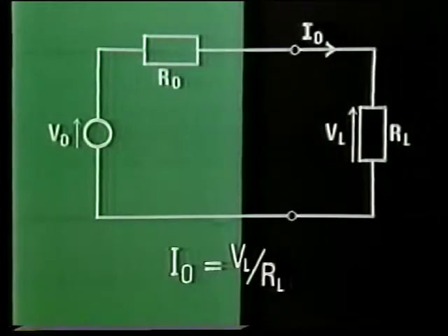If the voltage gain, and hence VL, don't change with load, the current gain must change inversely as the load resistance. We tend to call the amplifier a voltage amplifier because its voltage gain is well defined and does not change with load. But the fact that it amplifies voltage does not mean that it has no current gain. Far from it. As you've seen, the current gain could be as large as 50, whereas in fact the voltage gain of this amplifier is only 10.